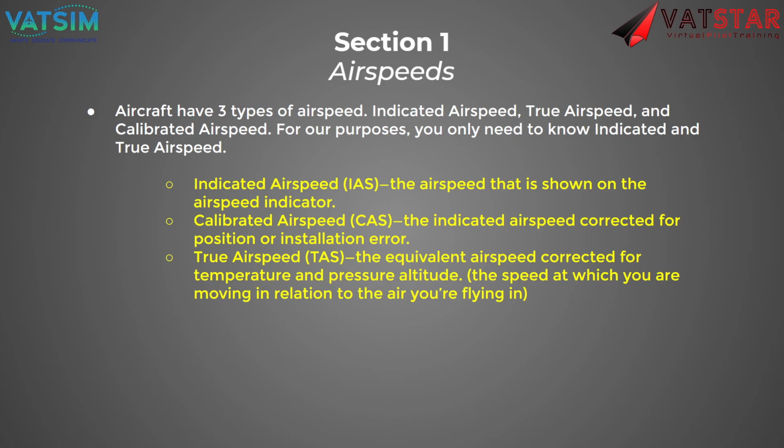Do any of the instruments actually show you true airspeed, or do you have to post-calculate that? You can. On some airspeed indicators, there's a little dial on the bottom left of the airspeed indicator, and you can put in the temperature at the altitude you're at, and that will read out true airspeed.